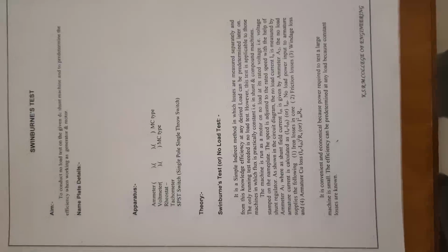And the other names for Swinburne test are no load test or predetermination test. So with the help of this test, we can estimate the efficiency of the machine from no load to full load without actually applying the load. So with the help of no load input itself, we are able to estimate the efficiency at different load conditions.